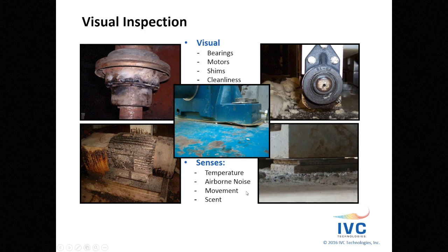You're also authorized and completely capable of using your other senses. Does it feel hot? Is the temperature abnormally high? Is there a lot of abnormal noise? Is there excessive movement that you can visually see? Is there an abnormal smell? A lot of times if there's an electrical issue or things are burning, you get that acrid scent.